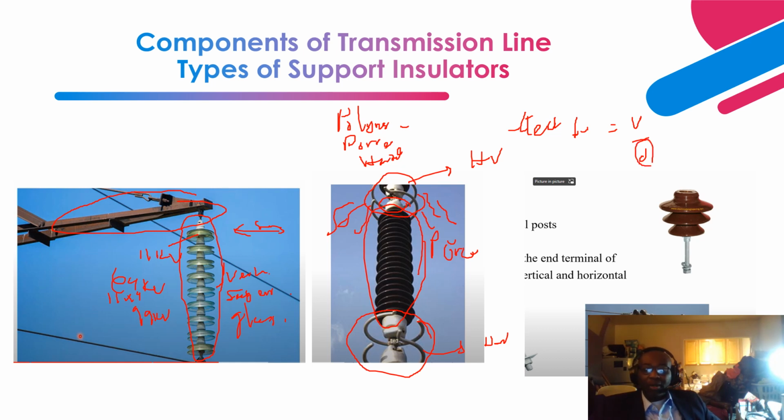So the smaller the distance, the higher your electric field stress, right? And the goal is to reduce the electric field stress to a withstand capability. So that is why they put these corona rings. That basically increases the distance, increases this D over here, so that the electric field decreases around these external porcelain insulators to prevent corona from occurring, which can damage the external porcelain insulator.